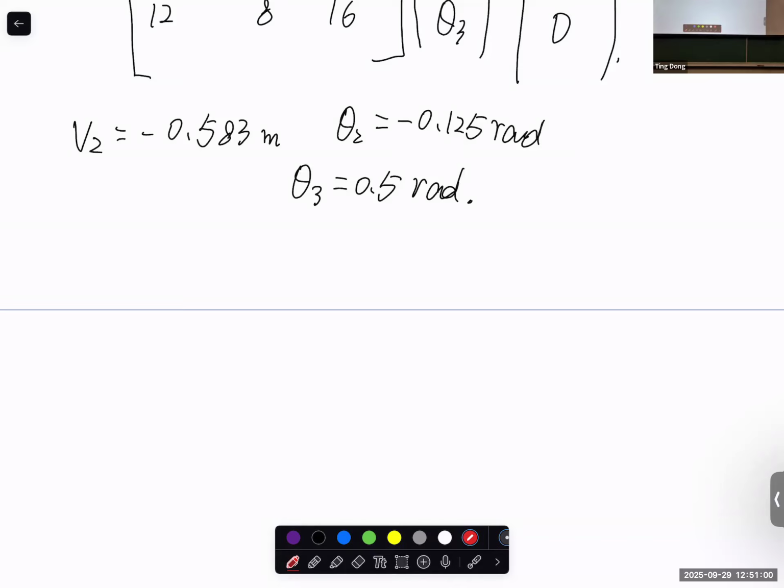So we're done with two topics in the beam chapter. The first topic we talked about before the exam was beam interpolation. Basically, we assume that if we know the nodal degrees of freedom, let's say for one element, V1, theta 1, V2, theta 2, we know how to do the interpolation to find the V and theta at any point in between. The second topic we talked about in the last class was, let's say, back to KQ equal to F.